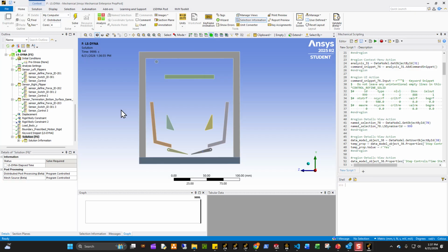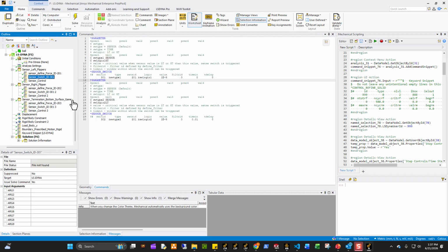This is the last part of my sensor video, right? But the beauty of sensor, that's why I spent 4 videos on this, is I realized there are so many different ways in which we can apply this sensor-based technology, these sensor-based techniques, to different problems. In this case, I use 3 different sensors to control the left, the right, and the middle. And I use a special logic, following the Dynamos example, to turn on and turn off specific boundary conditions based on a trick and a delay that I can essentially add.